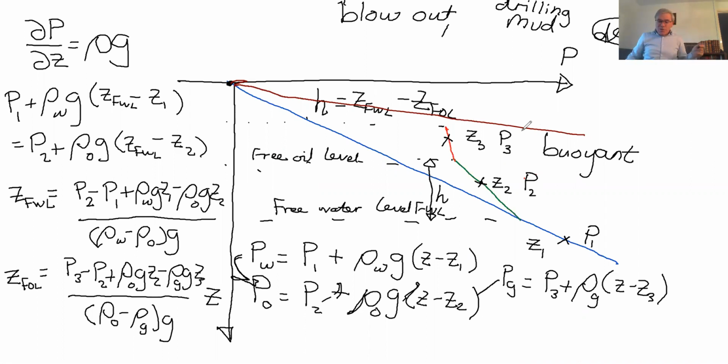So what do you do to make the fluid dense? You normally have what's called barytes, barium sulfates. These barytes are very dense. They simply make a dense mixture, and this can be dissolved, as I said before, in either water or oil. So you have these barytes that make the dense fluid.